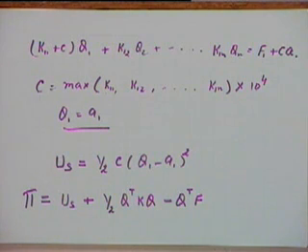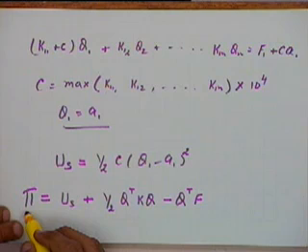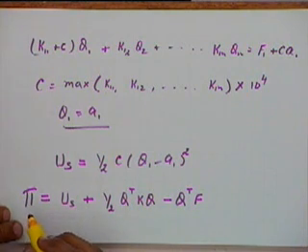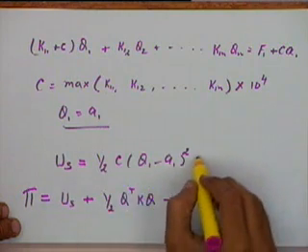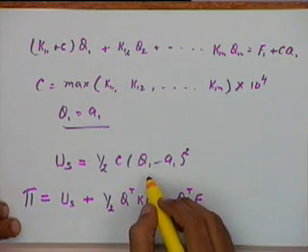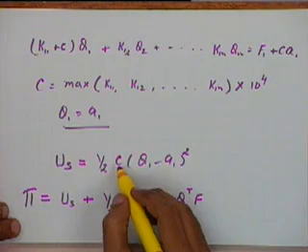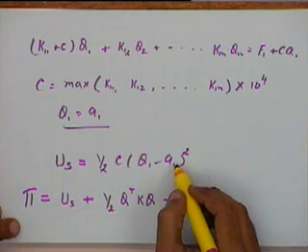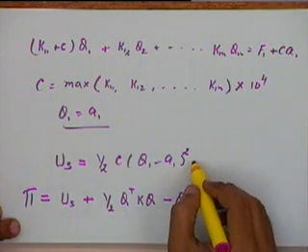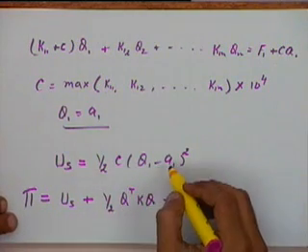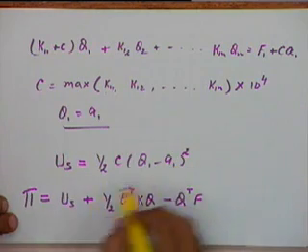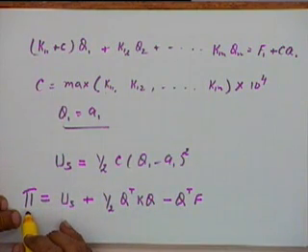Okay. Now in this potential energy expression, we are trying to minimize the potential energy, and this will be minimum only when this term becomes very small. So if c is large and q1 minus a1 is not equal to 0, this term will become very large. Okay, so only when q1 tends to be equal to a1 will we be able to minimize the potential energy.